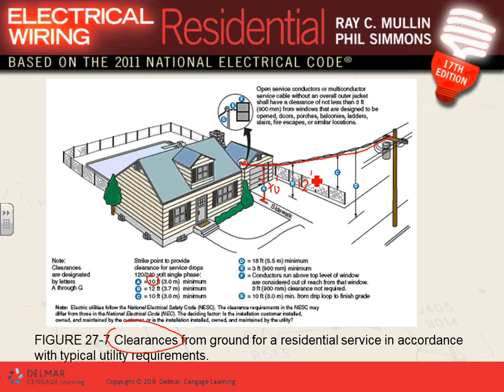If you have fences, can you guys see also, right above the fence, you have to have 10 feet right above the fence if you have a fence. So why? Because you don't want Chad to stand on the fence and grab on the power lines. So that's your A, B, C, and then you have D, 18. Can you guys see the 18 feet over the alleys in the back of your house? There will be, if there's an alley, or commercial streets and so forth, you have to clear it by 18 feet. So who's going to be controlling this? The utilities, most likely the utilities. So that's 18 feet. Any comments, any questions, guys, about the clearances?